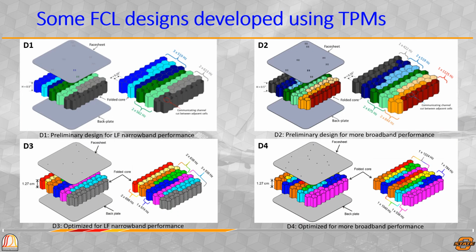Using these LFPs, 4 designs were manufactured and tested. Half-inch cells that are 1/4 of an inch in diameter were connected to get the desired length of the resonator. Design 1 and 2 were initial designs using the baseline LFP, along with previous knowledge and experience, whereas Design 3 was selected solely using the cubic lower bound LFP to get a narrow band low frequency, and Design 4 was selected using the average frequency normalization to get a wide broadband performance. These manufactured designs were tested and matched very well to the simulated results.